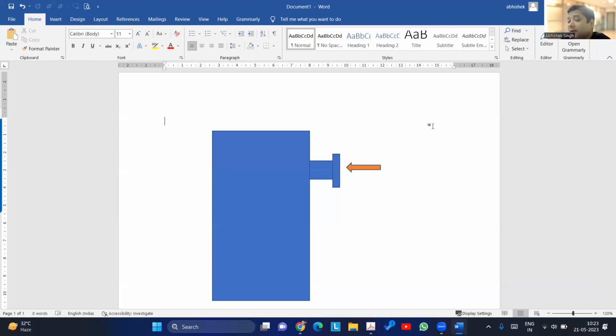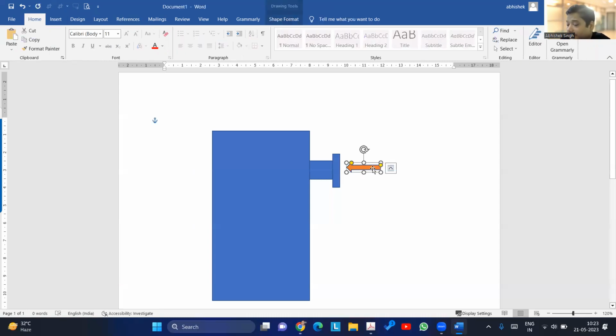There is external load coming, which is this, on that nozzle. It is coming because of the piping connected to that. This load value is given. So what all calculations do you need to perform in this scenario? I'm saying balancing forces and moments.